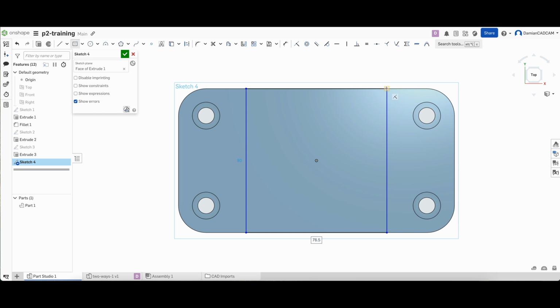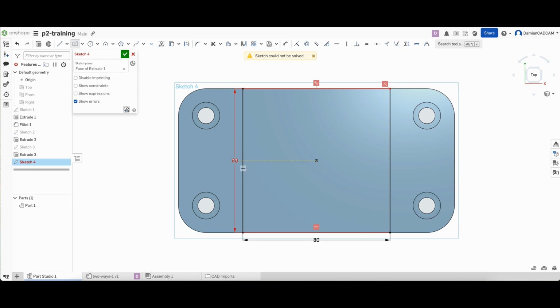And regarding this dimension, I can no longer change this dimension because this dimension results directly from the solid's dimension. And now we can change this dimension. To do this, I hover the cursor here and enter 80 millimeters as the value for this dimension and press enter. As for this dimension, the edit field for this dimension is now active, but notice that if I enter a different value here, an error will appear. We cannot do this because this dimension is a resulting dimension and derives from the constraint. I select this dimension and press delete.